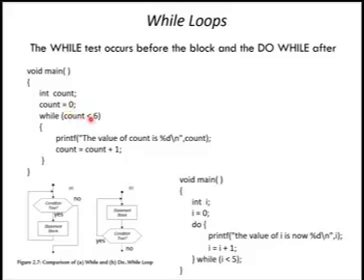So x is equal to any value coming from RC0. And then you do a comparison. If x is equal to 1, then do this: RD0 must be equal to 1. So note the difference: double equal to, single equal to. With double equal to, you are doing a comparison. With single equal to, you are assigning a value to the variable. So if the condition holds, the statement is executed. This one you will learn later.